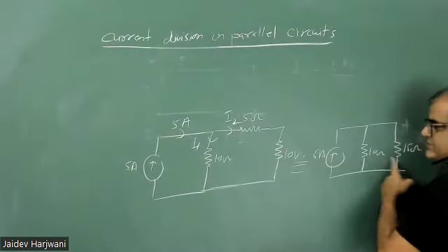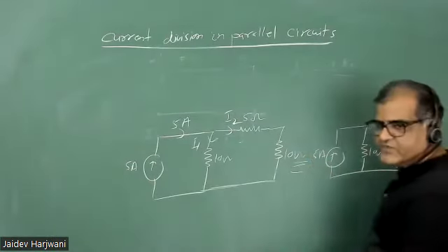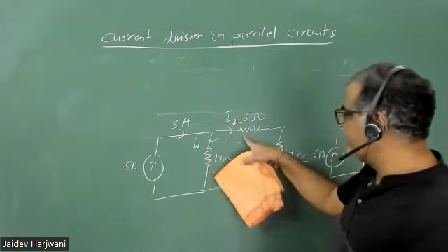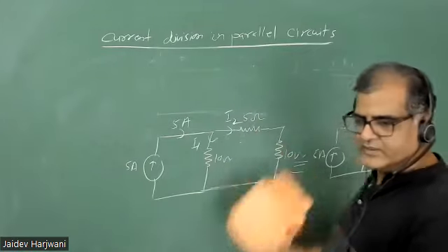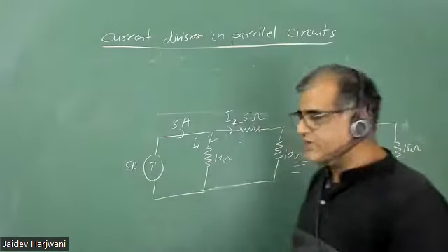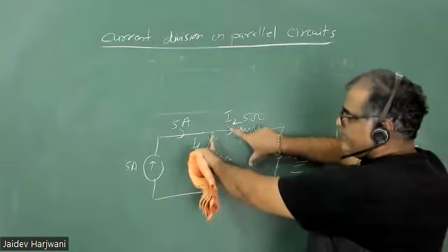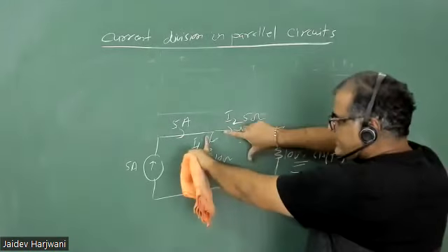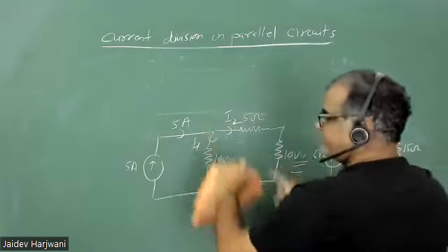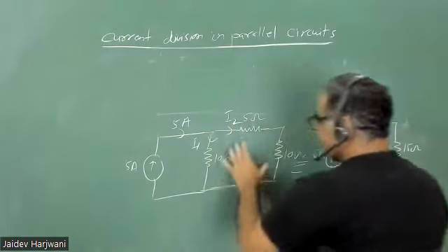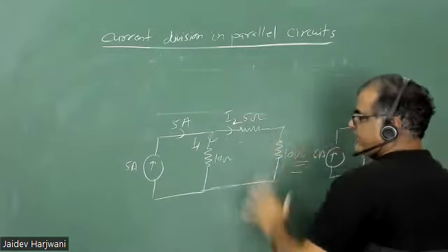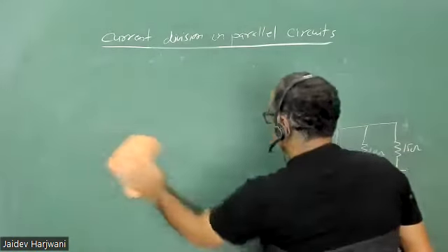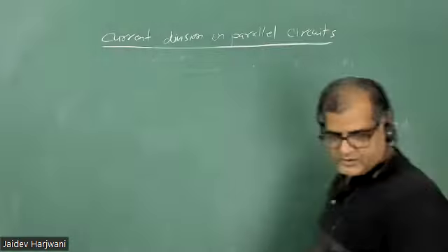So this is the same circuit, and the current will be the same. Here also the same current flowing. I1 was 3, here 2 ampere. That's why I'm telling you to understand branches. How many branches are there? There are 2 branches: one branch, and this whole is one branch. The sum of resistance is the same. In this branch the resistance is 10, in this it is 15. So accordingly, you have to apply this law. Now let me increase the branches.